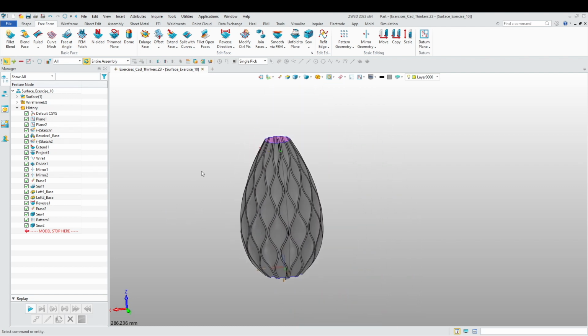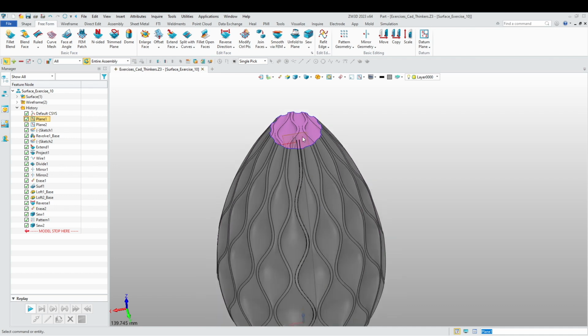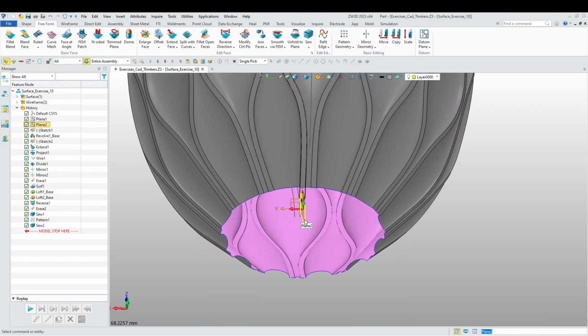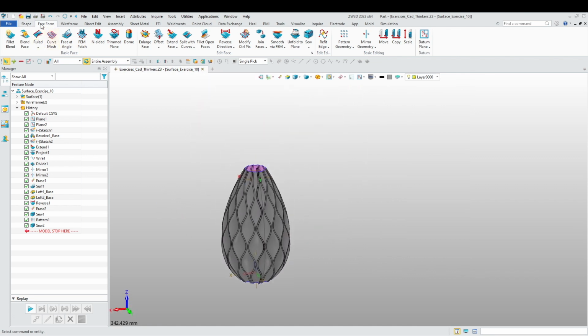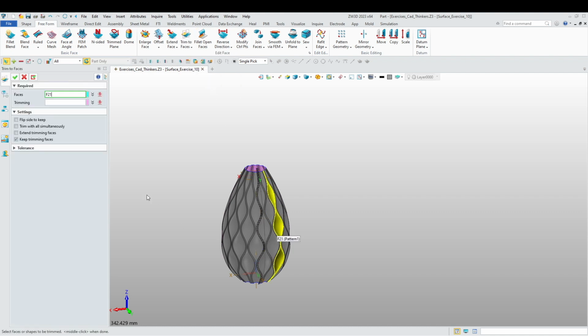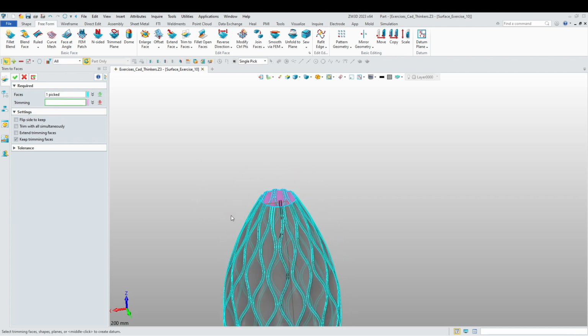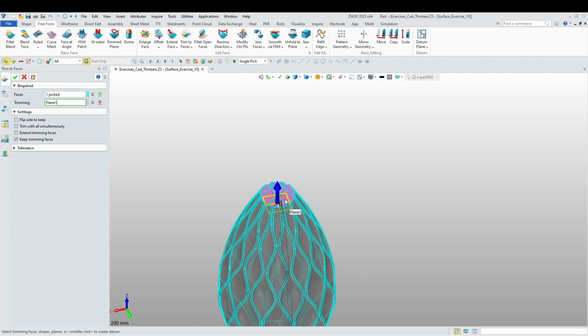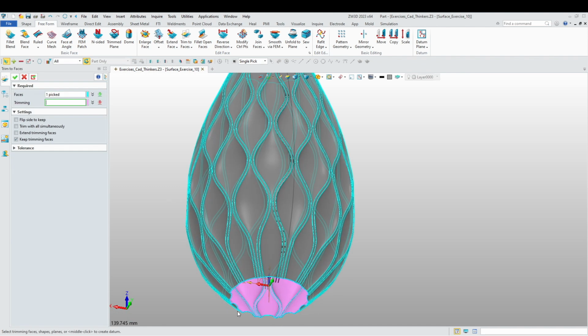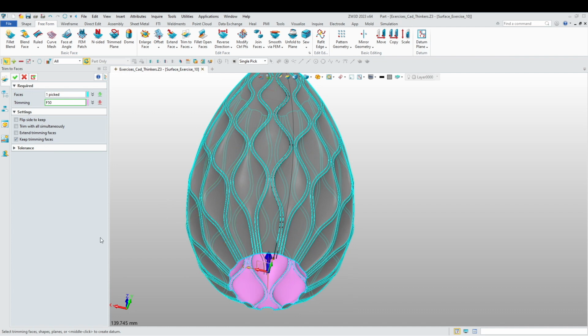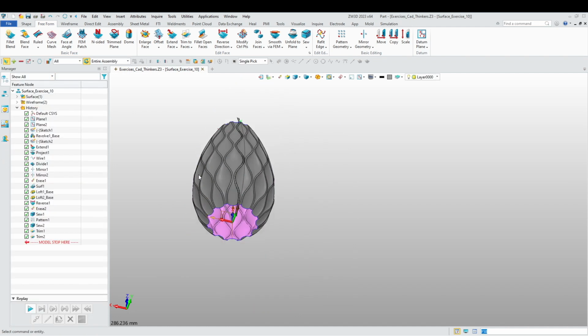And now we're going to use those planes that I created here, this one, and the bottom plane to cut off the edges, all right? Trim the edges. So let's go to trim two faces. Again, shape, I want this, and I want to trim it with this plane. Flip side to keep. There we go. Trim again, this time with this plane, and there we have it. Okay.